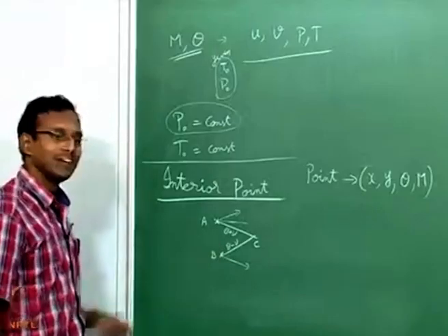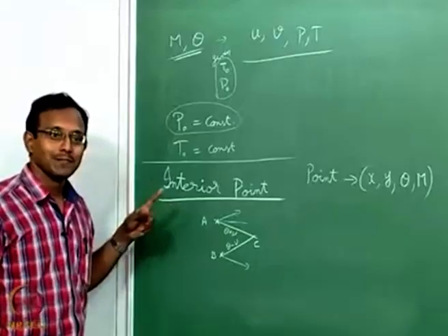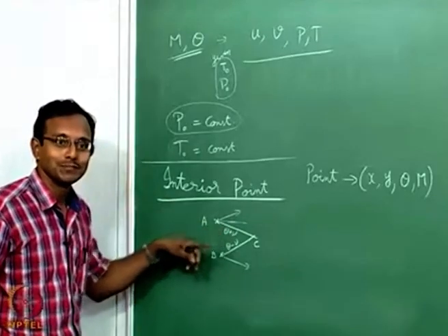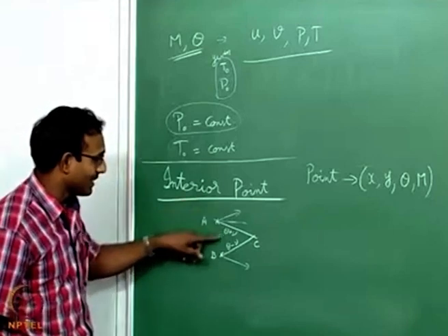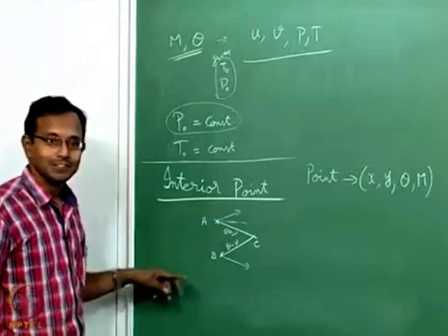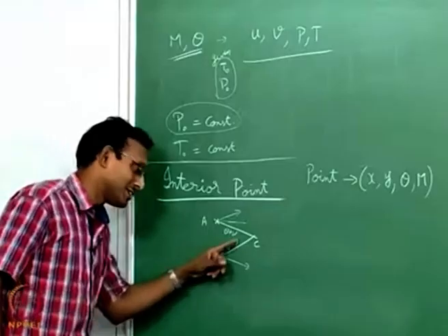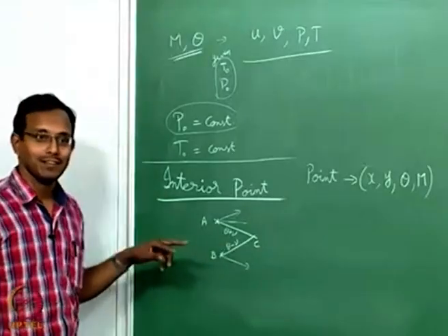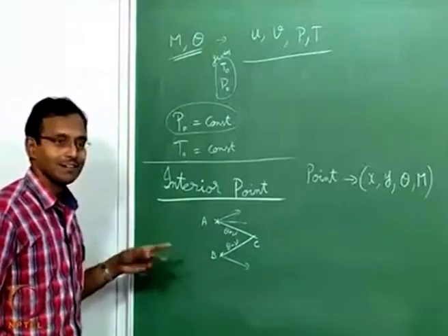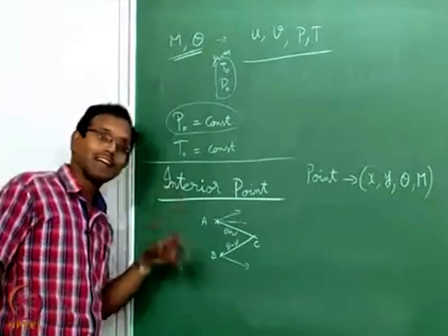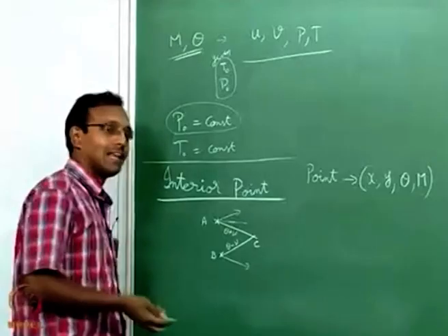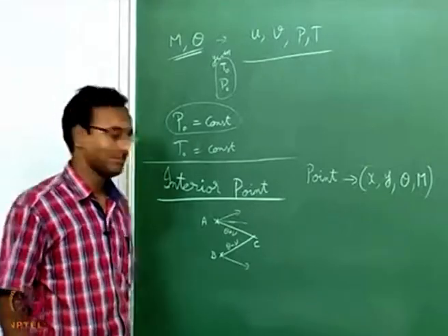I like to think about it as positive and negative because it makes sense to use the opposite sign in theta plus nu versus theta minus nu. If it is a negative characteristic, it will have theta plus nu constant. If it is a positive characteristic, then it will have theta minus nu constant. That is why I prefer to use positive and negative. But it will get confusing after some time, and angles are not going to remain positive or negative. There it will help to have left running versus right running.